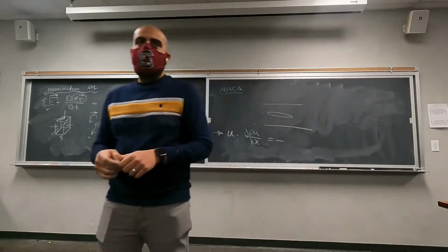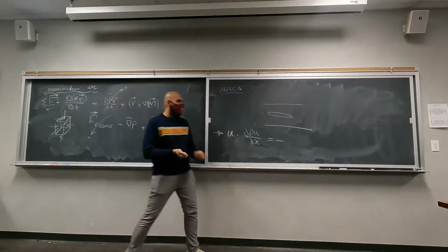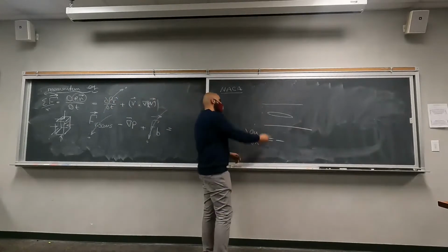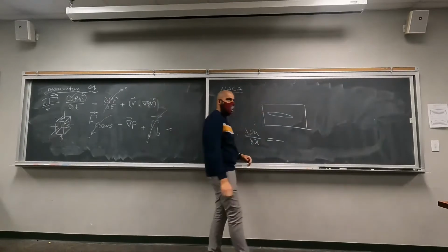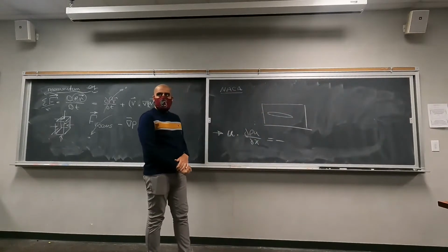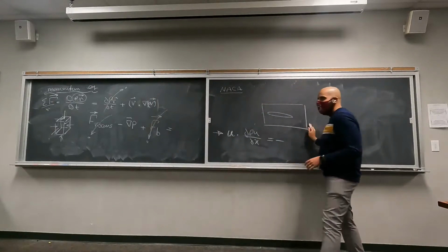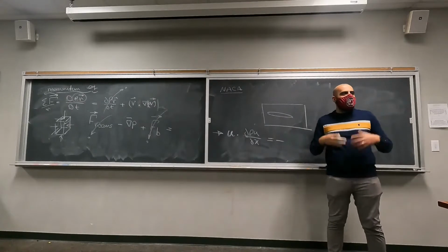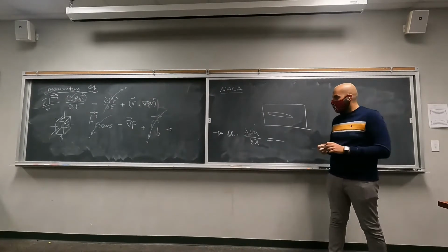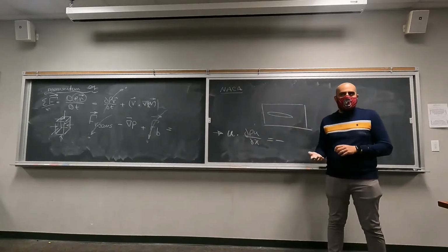If we can come up with a way to get the velocity profile here in the inlet of the wind tunnel and the velocity profile here in the outlet of the wind tunnel, and then subtract the two, we are going to find the momentum that has been lost through this equation, right? And that momentum loss is essentially your drag.